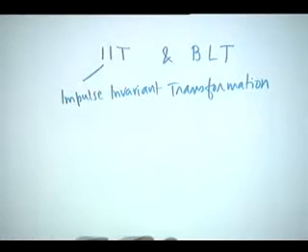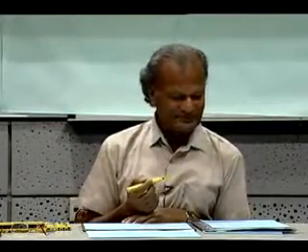Most of the IIR filters for biomedical signal processing, for example, people do not want to go into the complication of bilinear transformation, they simply use impulse invariant transformation, and if it works for an engineer, anything that works is good enough. So, people still use IIT. Mitra's second edition, for example, does not discuss IIT at all, he only uses bilinear transformation. That is one reason why I am asking you to take careful notes.